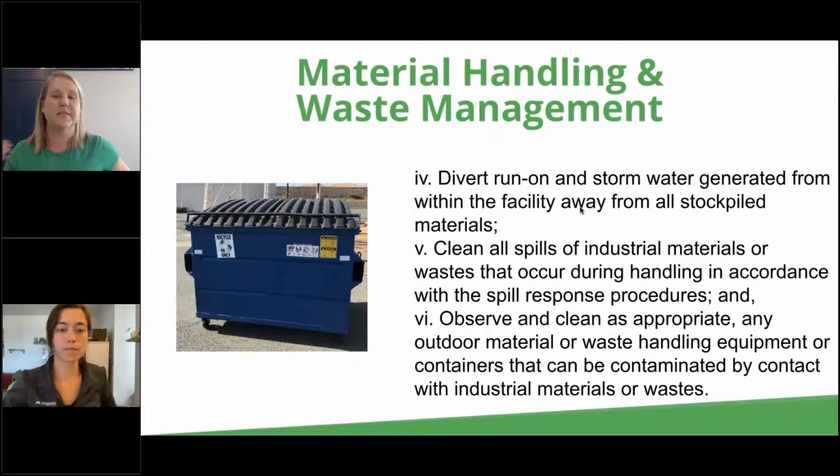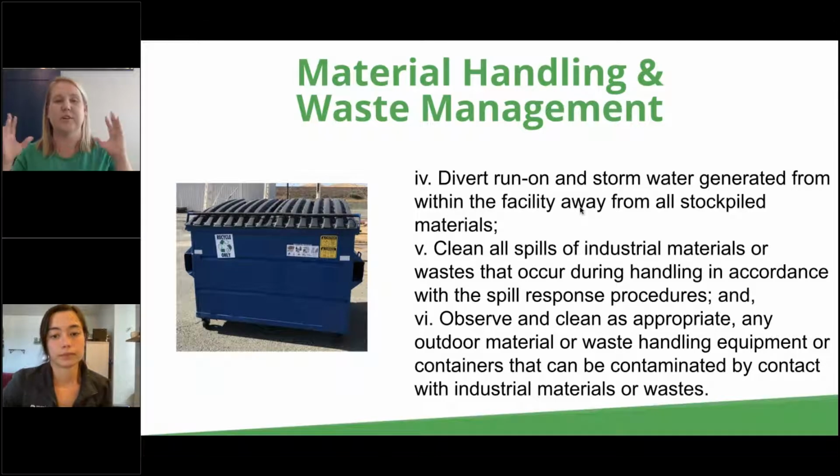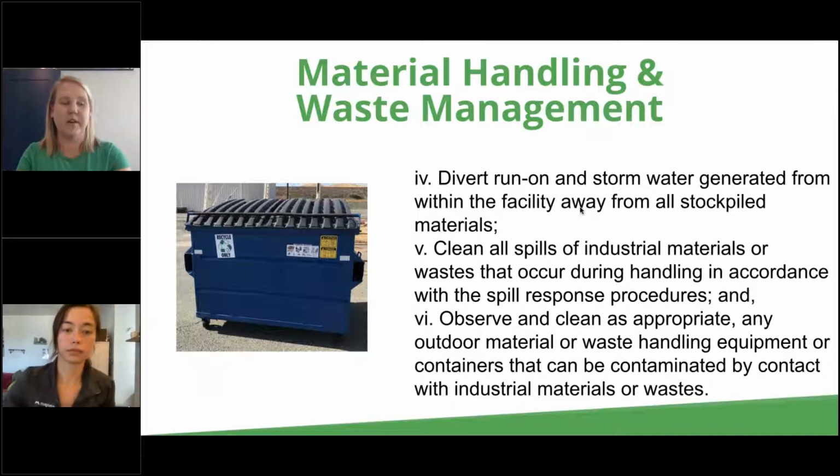And again, you want to divert runoff away from any stockpiled material. So if you have areas where you're storing, if you've got metal storage or anything outside, you want to make sure you're kind of bermed it up and keep the stormwater from running right through it. You want to be sure, again, to clean up spills as soon as they occur. And you want to observe and clean as appropriate any outdoor material or waste handling equipment that could contain industrial materials or waste. So we want to take a really critical look at what's going on site.